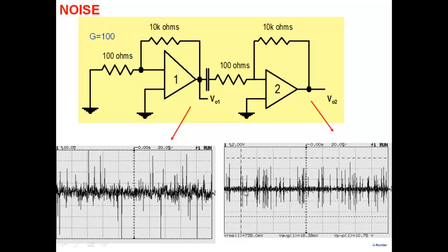The source of noise that you see here is all these resistors inside, and transistors and diodes inside here. Another source of noise which is not explicitly shown here is that these op-amps are powered by a power supply. The power supply that you think is 12 volt is not really 12 volt. That also has noise in it. And the noise from the power supply gets into your amplifier and then appears over here. So that could be another source here, the noise getting from the power supply also. Alright, so this is something to keep in mind.